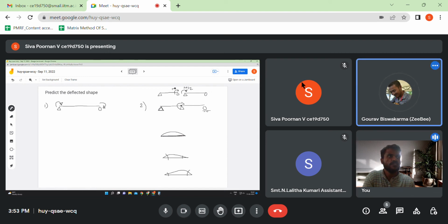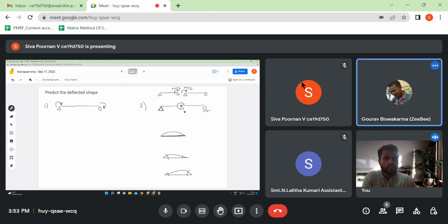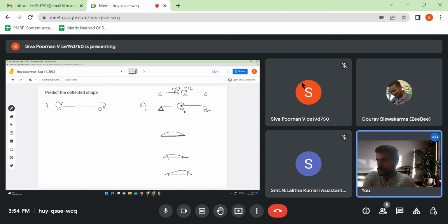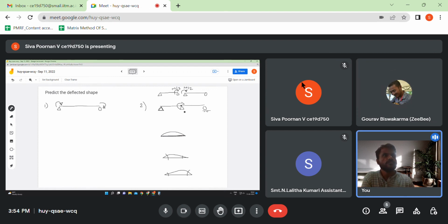This is similar to what we have studied in the basics of displacement methods. The total moment is trying to rotate both these things. The stiffness from both these members will contribute towards the entire structure. Are they in series or parallel? They are in parallel. Their stiffnesses will get added. So this moment is getting split into two things.